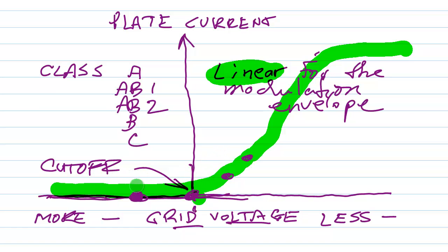You need a significant driving power in order to make a class C amplifier actually amplify. Otherwise, it won't amplify. It will literally attenuate the signal, or if you don't apply the waveform powerfully enough to get it out of cutoff, you won't get any output at all.